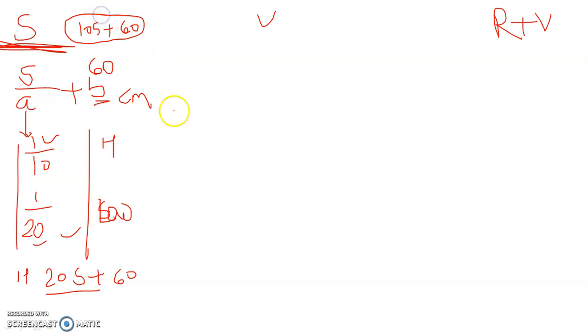And tell me by logic what should be the vertical distance, how far these two will be for heavy rainfall or low rainfall. So the distance between these two should be less for heavy rainfall than for scanty rainfall. By logic, for heavy rainfall the distance between these two will be lower, because you have to store the water here, and if you keep the distance higher then it will cause erosion in between these two areas. So 1 by 10 is for heavy rainfall and 1 by 20 is for low rainfall area.